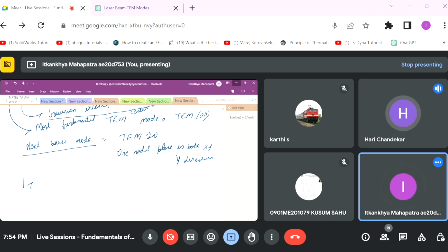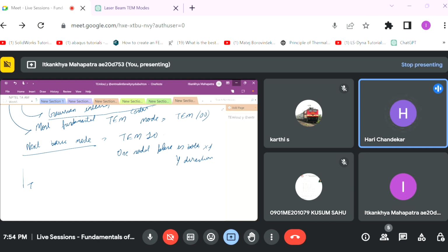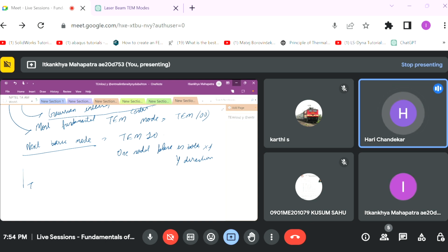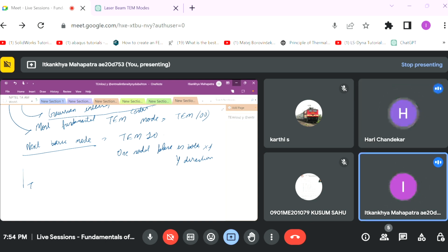But then the next value, once we get DP, critical exposure. That I get 7.77 millijoule per centimeter square. So that answer I get wrong as per the quiz, because that falls outside the range. The range given there for the correct answer is 6 to 7.